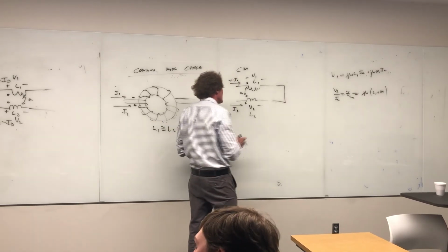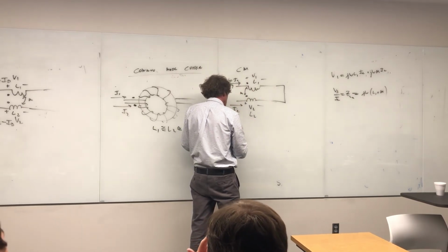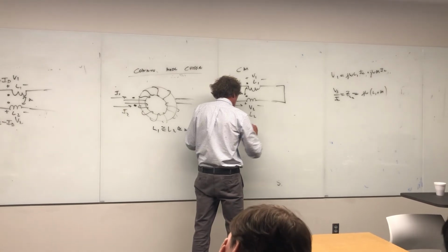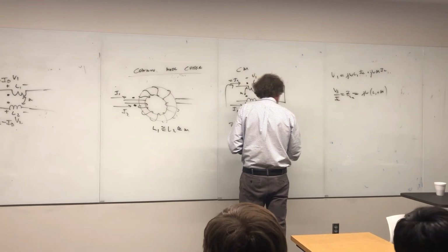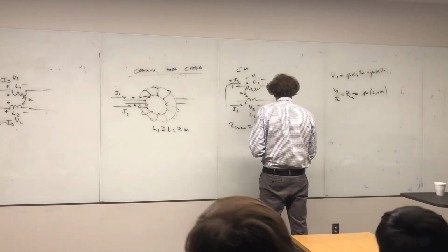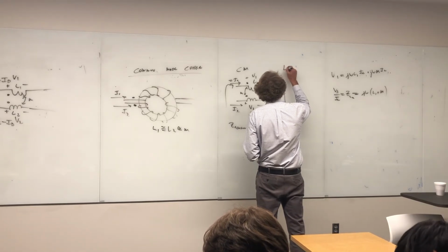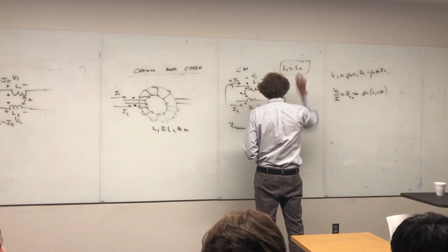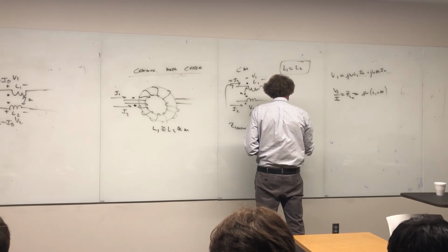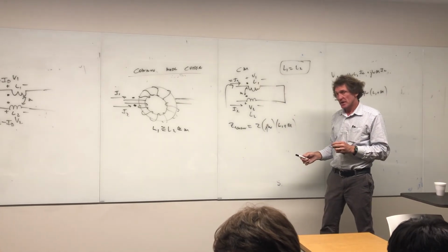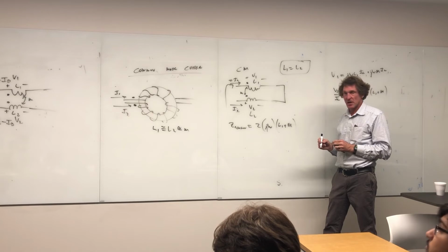So that means here, the net impedance, or the effect on the common mode current, Z common, this is the total, would be equal to 2 times J omega times L. Actually, I'm going to make L1 equal to L2 because that's the way it is in the real world all the time. So it's really going to be 2 times J omega (L1 plus M). And what this amounts to is, it's twice the impedance on this coil or this coil in common mode. So that's Z common.